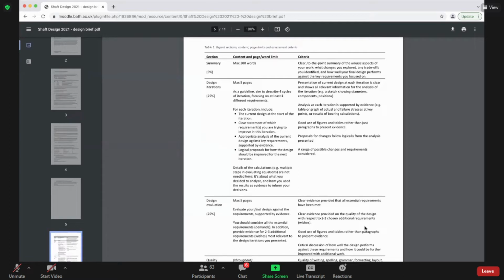Okay. So then there's a few miscellaneous questions about whether things are too big or too small. Maximum shaft diameter, and there's no particular maximum. If it gets too big, then it's not going to fit in the components. And you do have a guideline, a wish in the requirements list that the spacing from the chassis down to the shaft is no more than 90 millimeters. So I guess that puts a hard limit on the diameter of the shaft at 180 millimeters, but obviously less than that in practice because you have the sprockets that take up space.